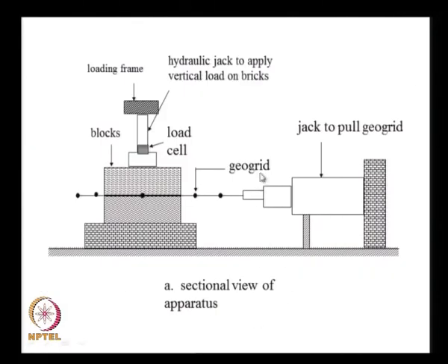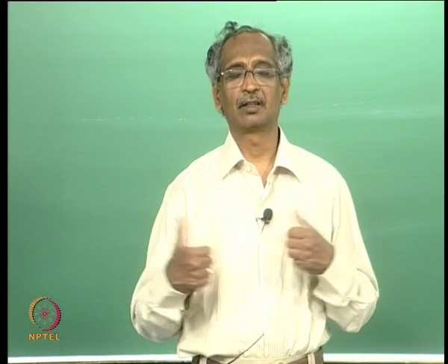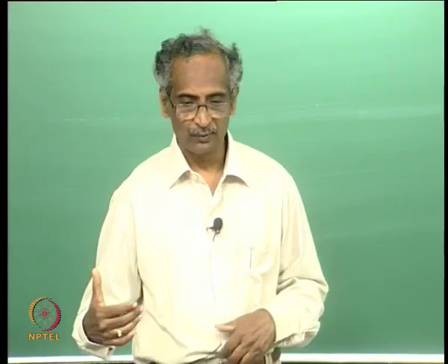And we need to use a lot of test data, and one important test data is on the connection strength between the facing blocks and the reinforcement.